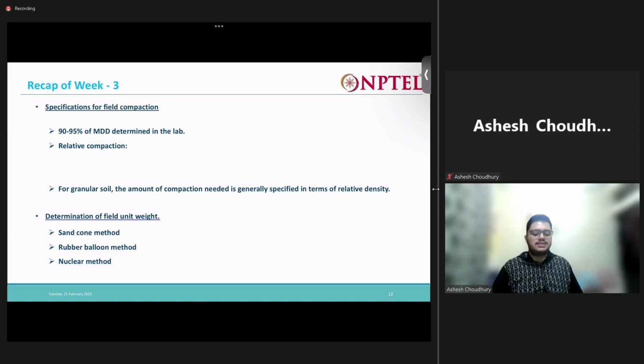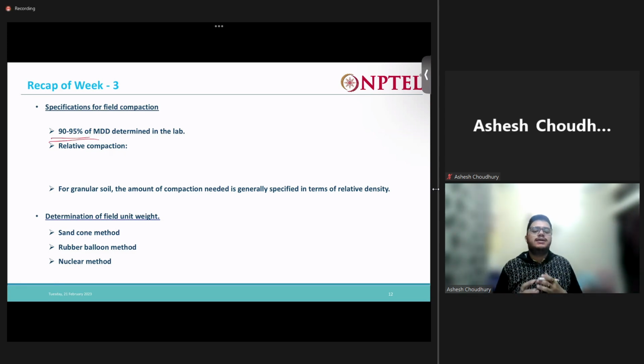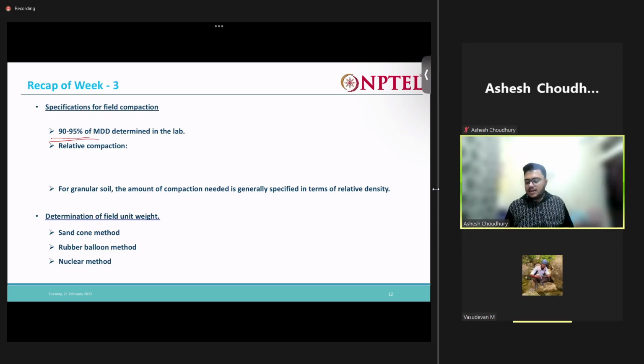So that dry density is generally 90 to 95% of the maximum dry density that is determined in the lab. Okay, so what I was telling is that this 90 to 95%, so you do the Proctor test in the lab. Okay, after doing the Proctor test you determine the maximum dry density.